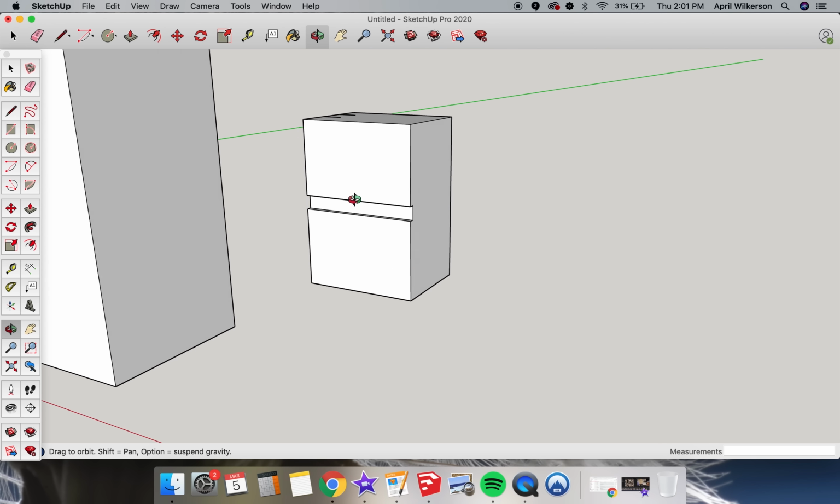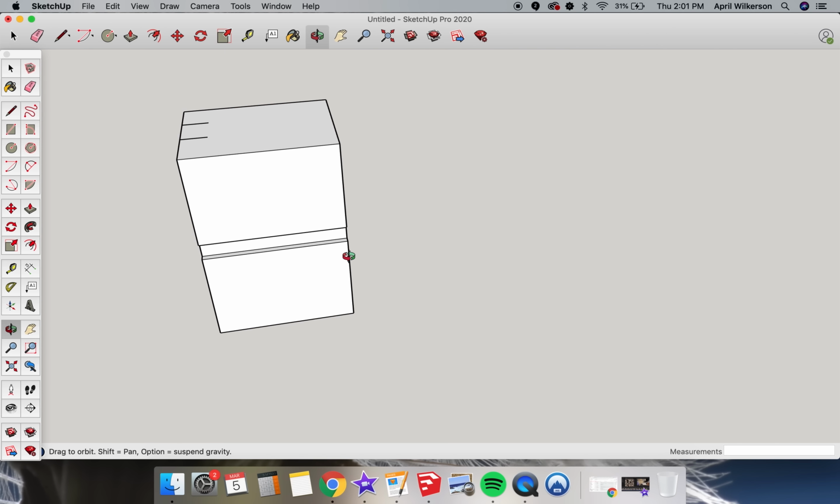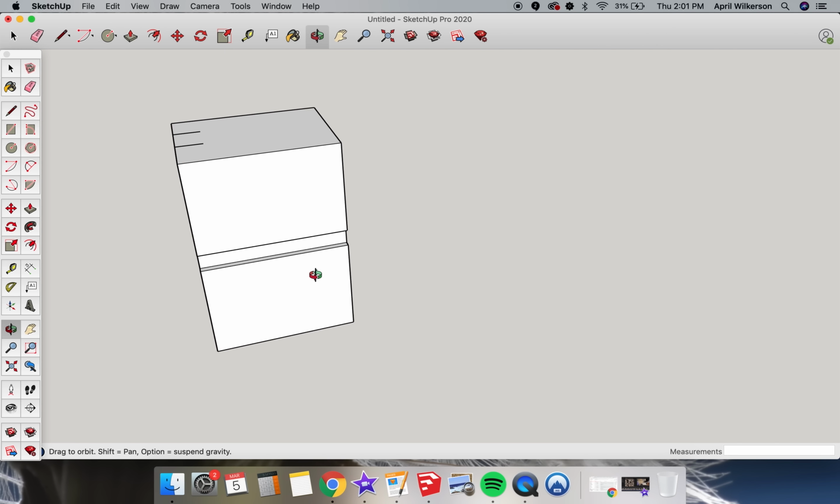That's an example of using the line tool to draw on a part, but now as an example of drawing something from scratch with it, let's draw a simple square. Hit L to bring up the line tool. Notice how the mouse icon changes to it. Click once to start drawing, then pull in any direction.